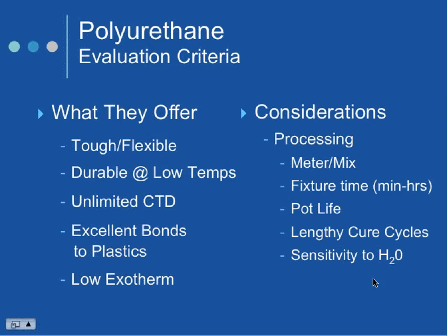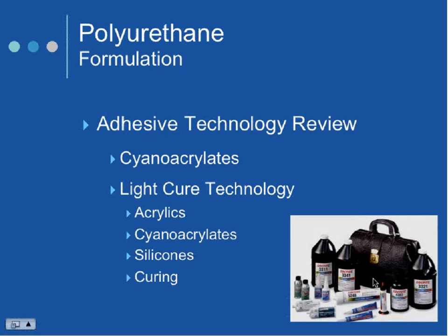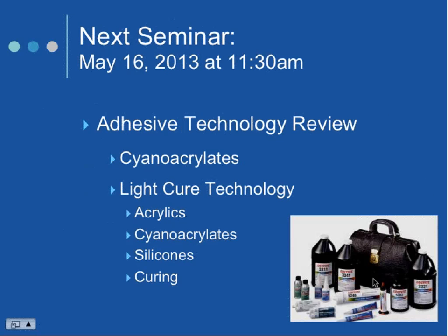Processing, same concerns and issues that you have with epoxies, but one that we added to it, which is sensitivity to moisture. You have to be very careful. We send those in a foil overpack to minimize any moisture exposure, because moisture will start to do strange things to it. It'll get bubbles in it. It'll create a very unattractive bond line if you're not careful. So they're kind of sensitive to work with. A couple of products, and I think that's it.